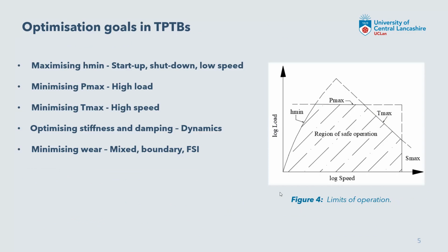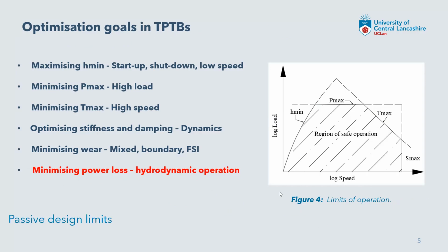There's also minimizing wear in the mixed and boundary regimes at low speed where you have surface contact. And what I'm looking at is minimizing power loss in the stable hydrodynamic operating regime, where you would tend to want the bearing to operate for most of its lifespan.